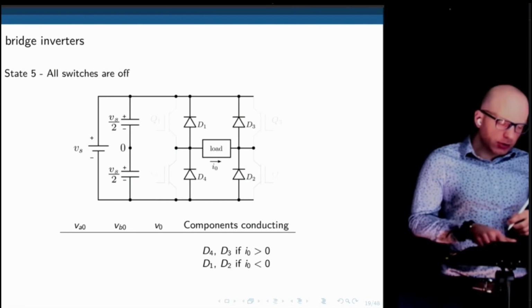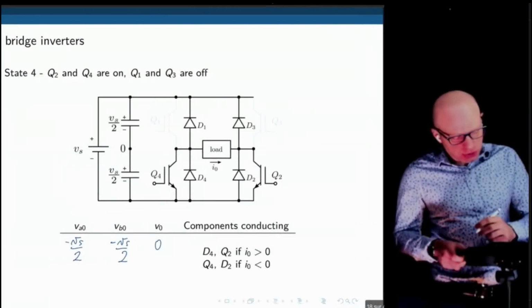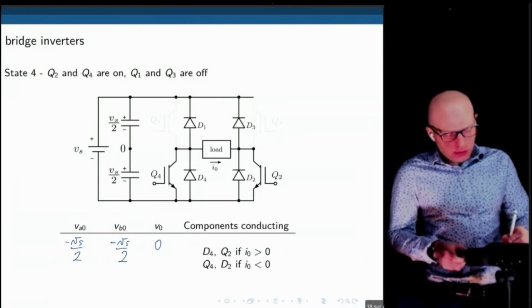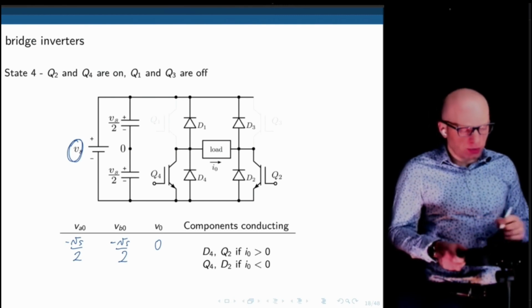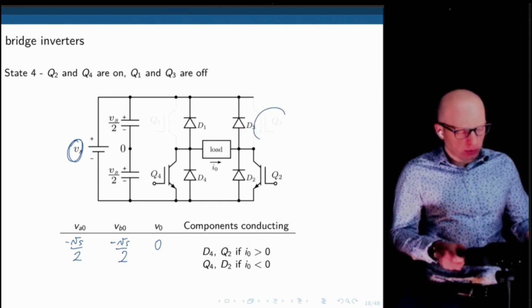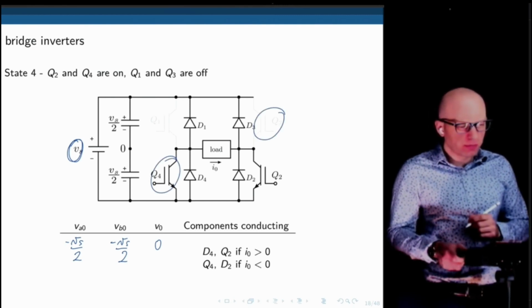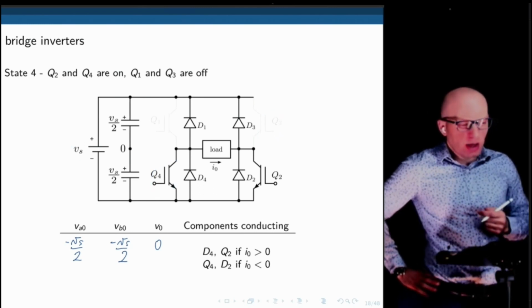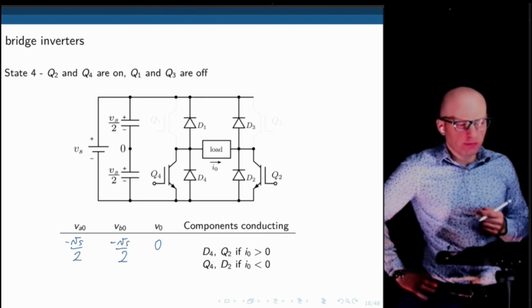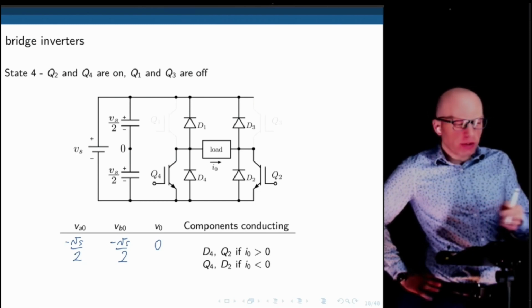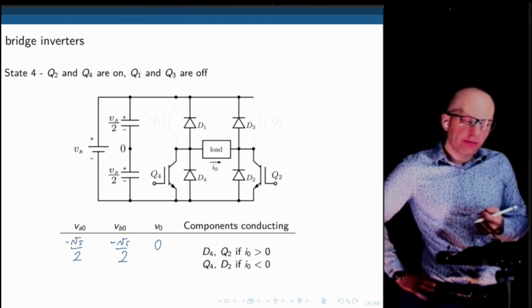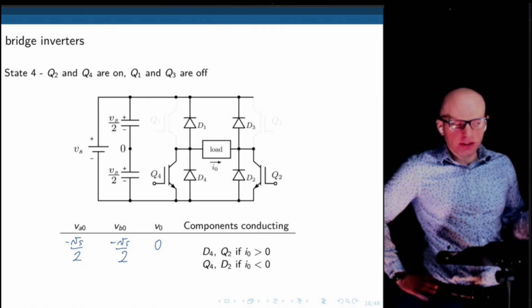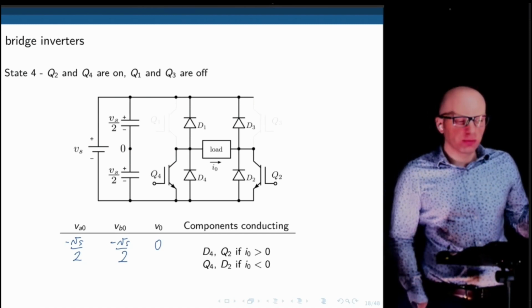Yes, that depends on the transistor you use, but that's a very good question, because in reality you don't see VS in the output. We see VS minus the voltage drops across both transistors. And depending on the transistor, it can be as high as 1.5 or 1.7 volts. So if you're powering this with a 5-volt power supply, be careful. You may not be delivering even half of your input to the output.